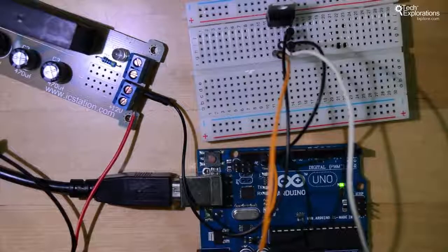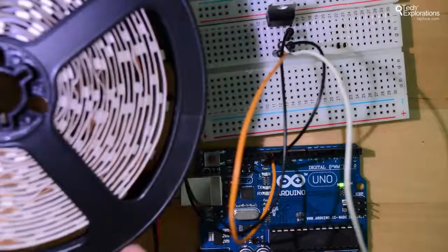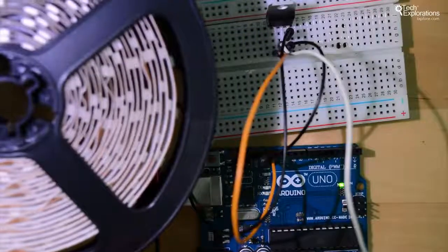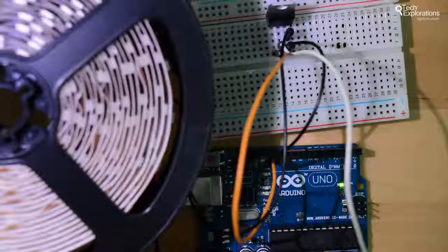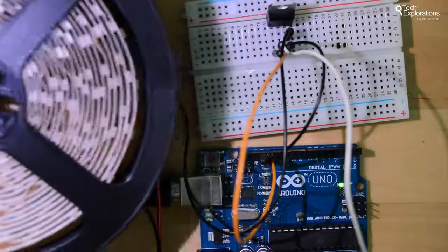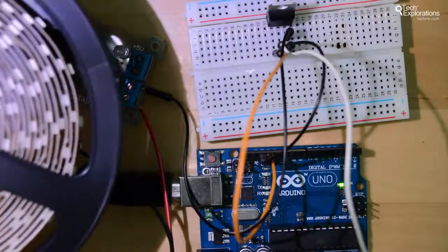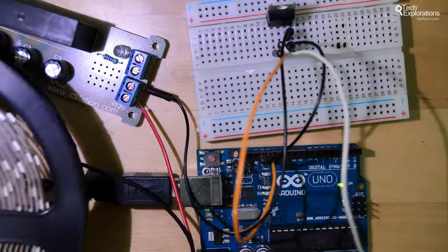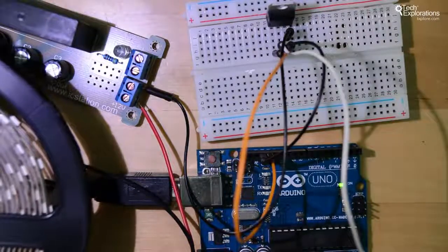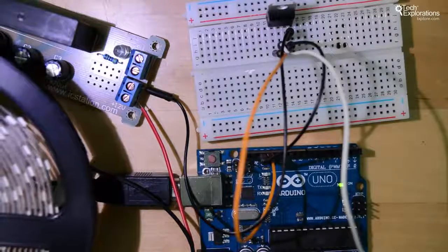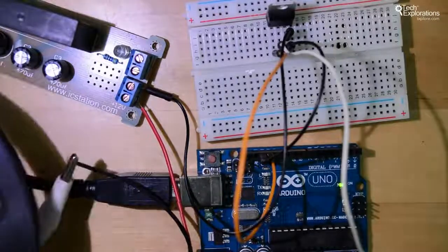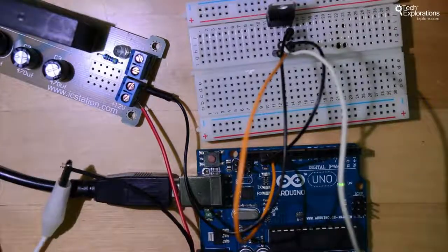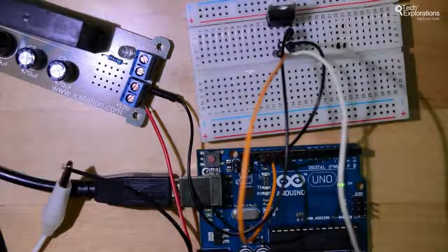Because I've got an LED strip, I want to be careful not to go too far above the 12 volts because I don't want to cause damage. Actually, I want to stay right on 12 volts. So that's why I'm not providing direct power from the wall power supplies to my LED strips. I want to have something in between to regulate that power. So that's where this comes in.